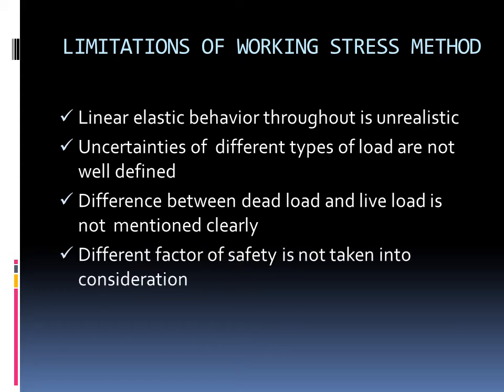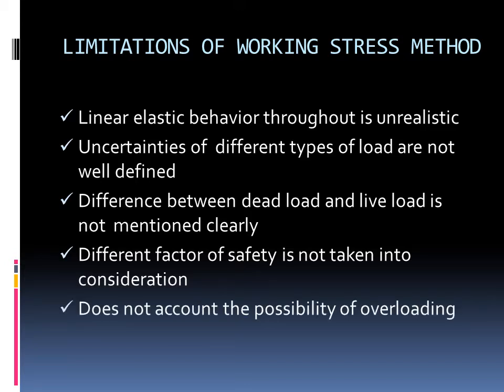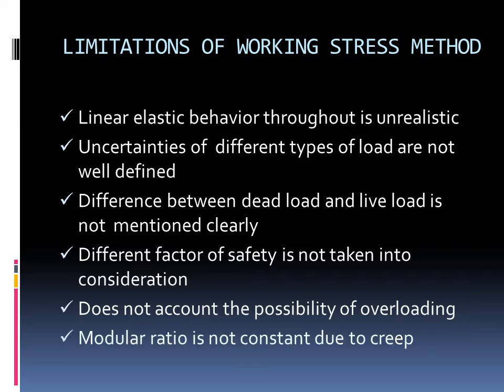And here a certain constant factor of safety was used, so it was also a limitation of this method that different factors of safety are not taken into consideration, and it does not account for the possibility of overloading. Oh, and one more thing, modular ratio was not constant due to creep. Now let's look into the next philosophy.